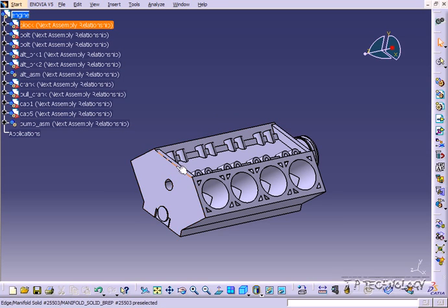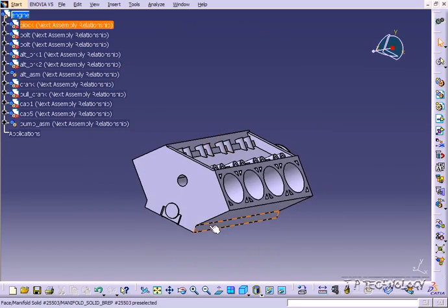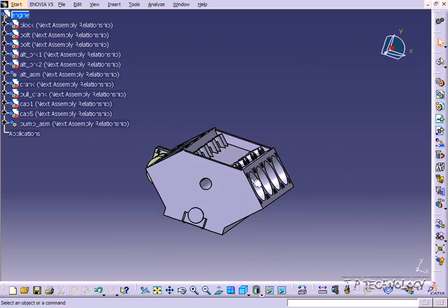You can use an edge too, but if you want to rotate through, say, a circle, get that center circle's axis in there and rotate about that. So you have to figure out which center line to rotate about for your axis, and which component you're going to use. In this case, we're going to be using the engine block. So we're going to put a center line axis down the engine block through the circle there.